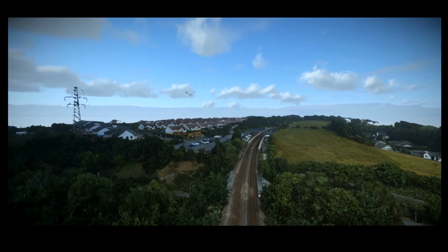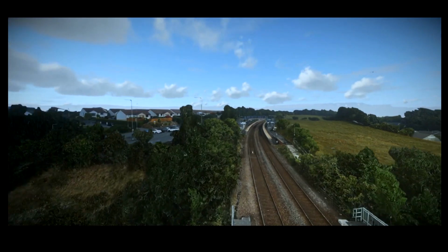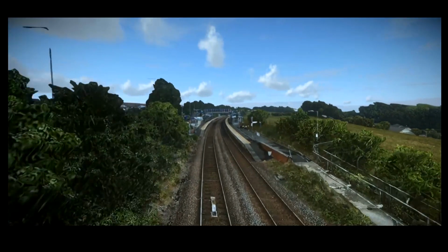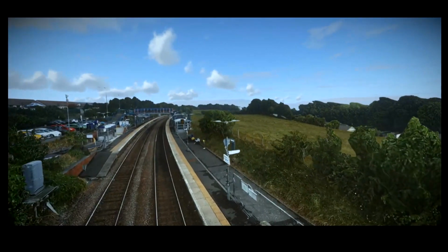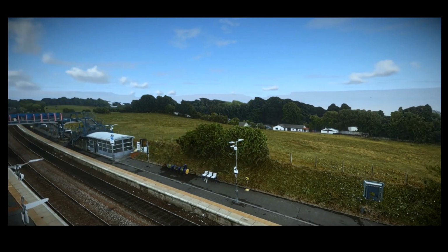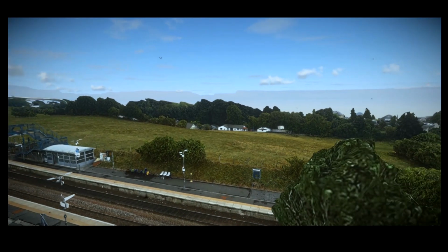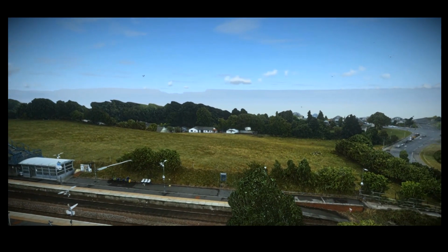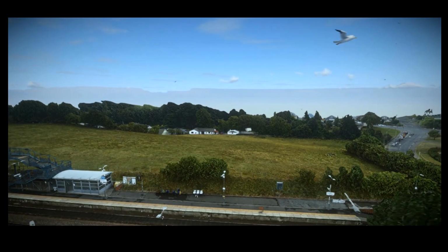So just to reiterate, this kind of service is available today, and depending on what your requirements are in terms of accuracy, you can readily achieve band 3 accuracy. In some cases, you can get down to band 2, band 1 accuracy with drones, but you do need a lot of control for that kind of stuff.